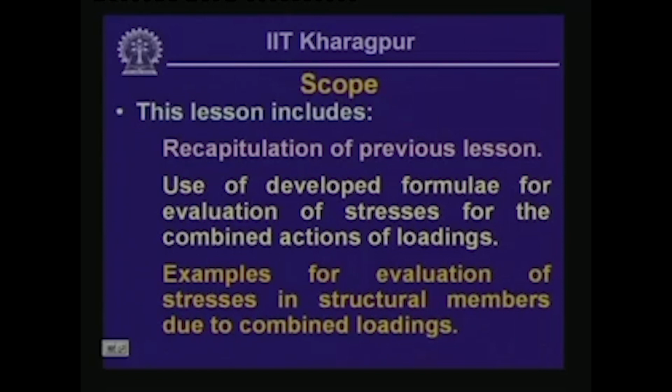As I told you in the last lesson, in the previous modules we developed formulae for the individual load cases: how to evaluate stress in a member subjected to axial load, or subjected to a twisting moment or torsion, or subjected to transverse loading, for which there will be bending in the member and thereby bending stresses or shear stresses, due to bending moment and shear force.